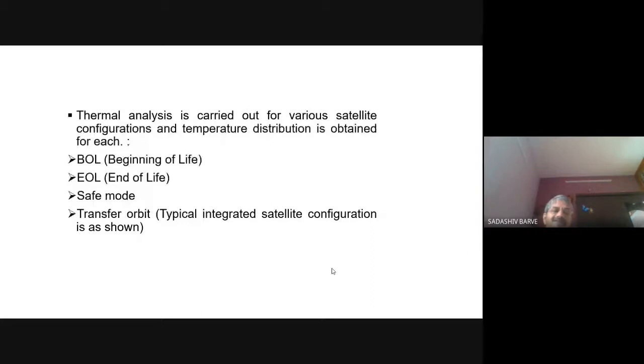But in case of INSAT, the satellite is generally injected into an orbit which is highly elliptical. Just for information, which is not important for a low Earth satellite, the satellite can be injected into a 300 to 10,000 kilometer highly elliptical orbit, and then every 2 or 3 days they keep doing thruster firing and orbit correction, raising the orbit altitude until they finally get it close to 36,000 kilometers.